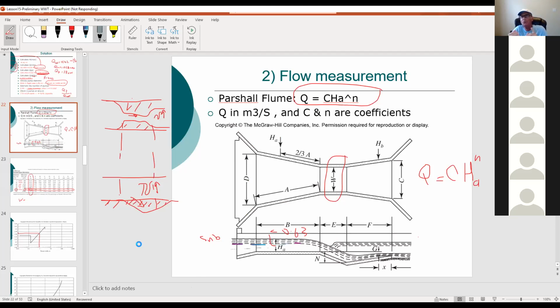So far you got your pumps, you got your Parshall flume. We need then, from the Parshall flume, to design the open channel where you can install your bar racks. All right. And after the bar racks, you need to design your grit removal. Okay. We'll do this next time. That's enough for today.